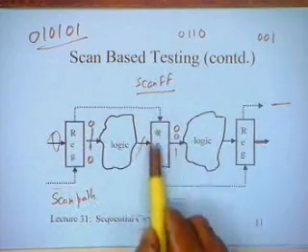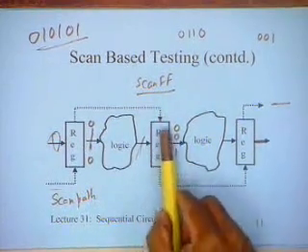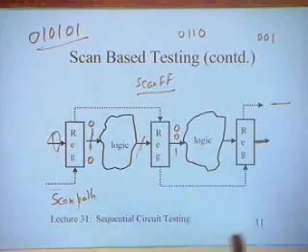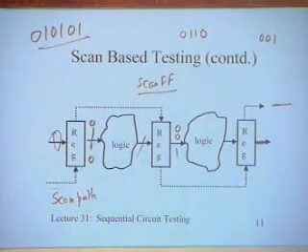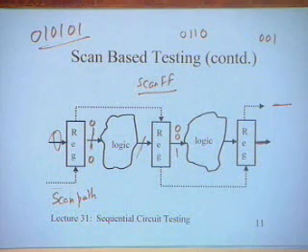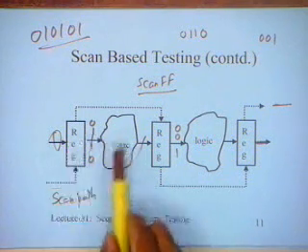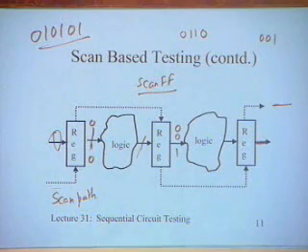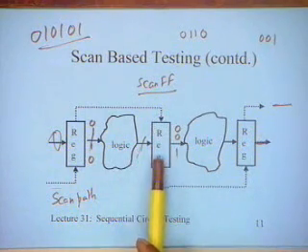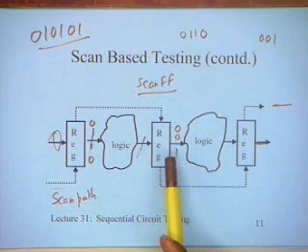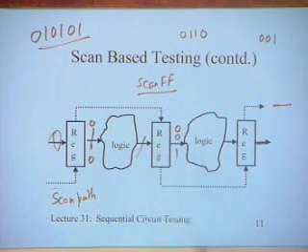And these outputs, this is also a random sequence generator, but the transitions it is performing, the numbers that it is generating, are modified by the outputs that are coming over here. So you apply some fixed number of test inputs over here, let us say 10 test inputs. These 10 test outputs are going to modify the number that is going to result over here, and that is called the signature of the circuit. I think we will discuss this with an example in the next class, but primarily it is a modification of the technique that we have discussed.